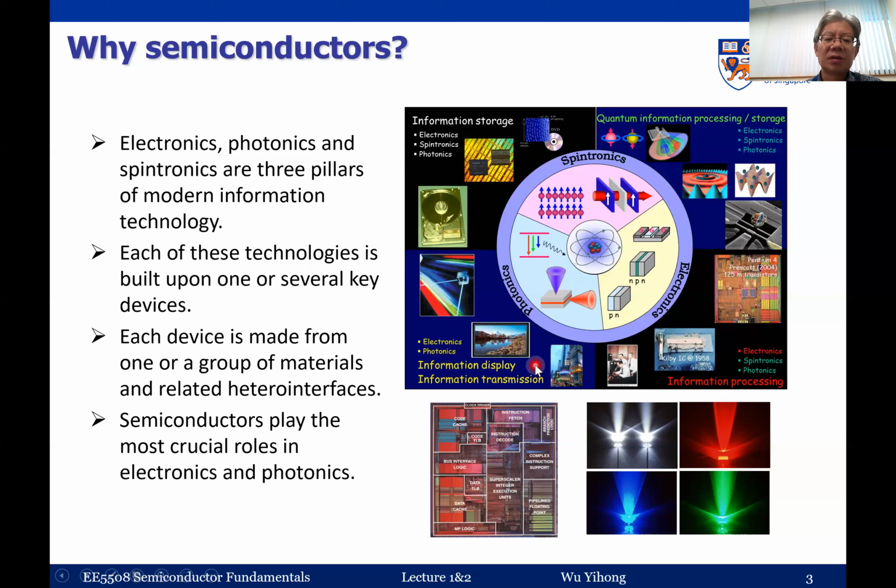And then of course you can use other types of lasers, but they are very bulky and very expensive. Also, it's difficult to control, right? This means when you do this communication, you have to switch the laser on and off at a very fast rate. And the semiconductor laser is really good at this, and it's low cost and compact, right? And also you can modulate the laser at a very high frequency, right? So that's the reason why this kind of semiconductor optoelectronic device is very, very important, right?